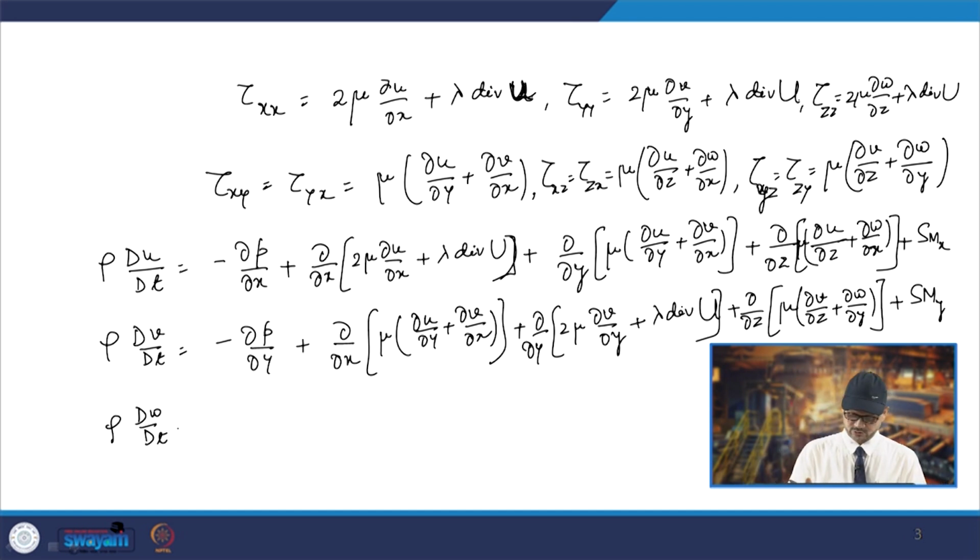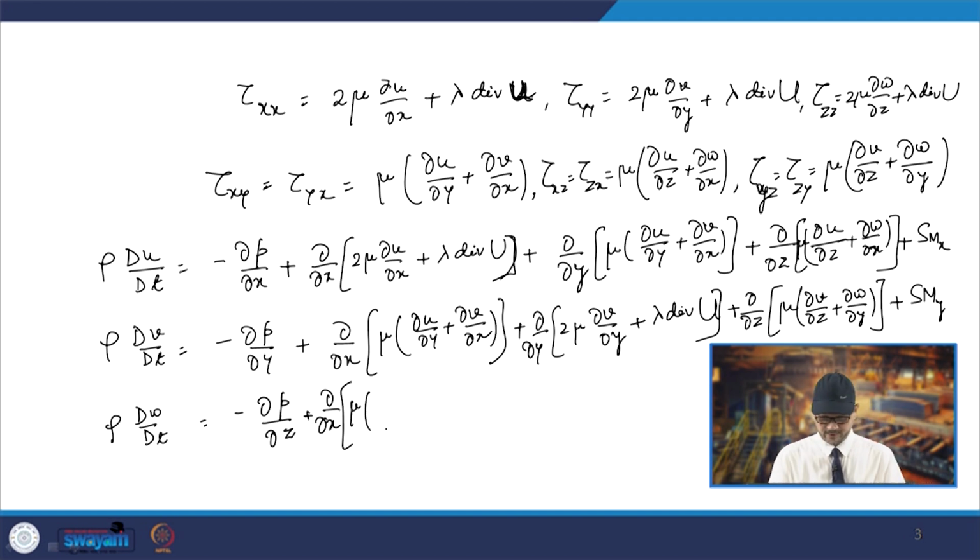So, this will be equal to minus of dou p by dou z plus dou by dou x of mu times dou u by dou z plus dou w by dou x.